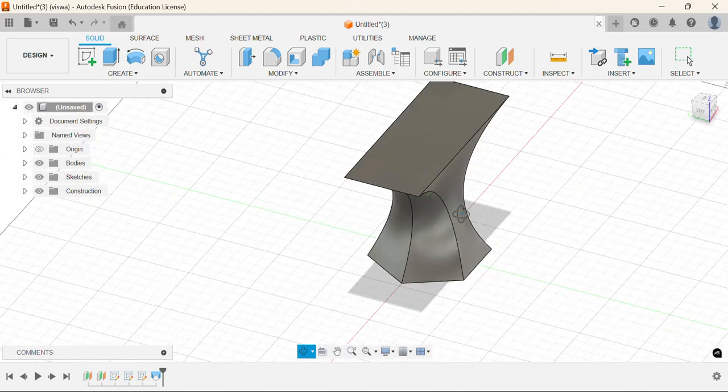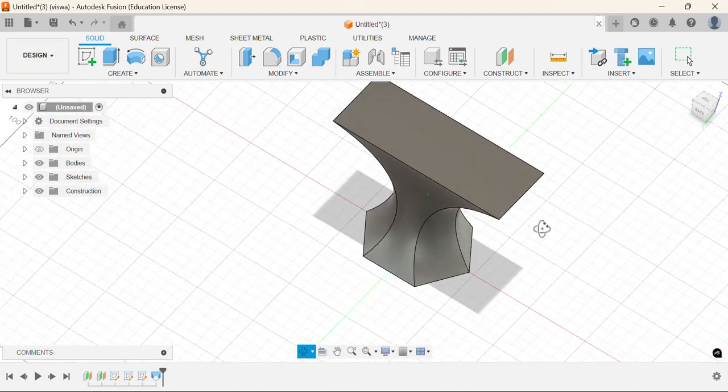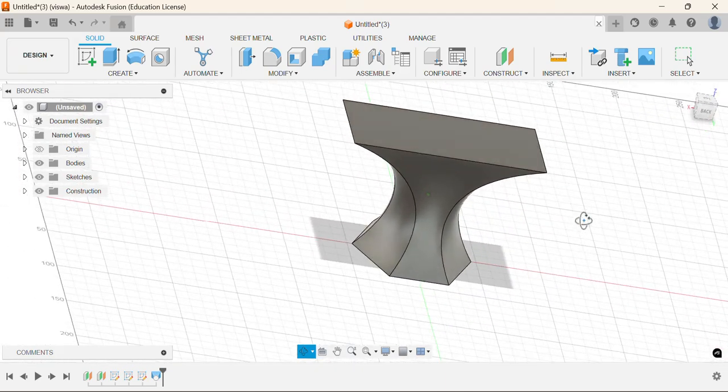So there are some elements in the design part which cannot be made in a single plane, and need to be a combination of multiple planar members. At those instances we can use this command called loft. So loft is used in very advanced design features to make them very easy. Only one thing, two planes must not be perpendicular in nature. If they are a little inclined also, the loft command can be used.